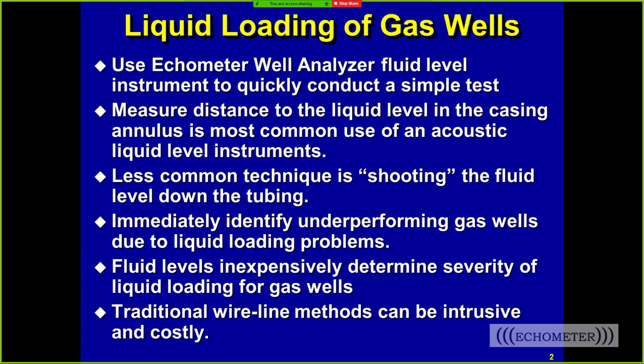Prior to 2000, I didn't really work a lot with gas wells. Most of the wells I worked with were rod pumping or wells with pumps onshore, typically, and we shot fluid levels down the casing annulus to determine pump intake pressure. It was a pretty simple test, and as a company, Amerada Hess, we were pretty happy with using acoustic fluid levels on producing wells.